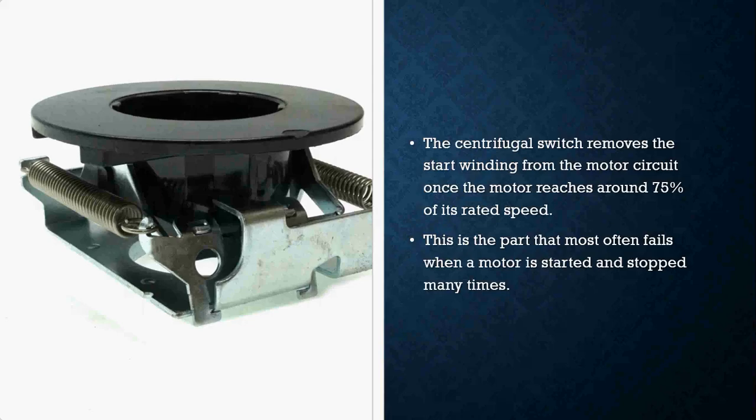Now, why do these things fail? It's because it moves. Remember, it's a normally closed switch, so every time that motor starts, that switch is going to open. Once that motor stops, it's going to close. It's going to keep doing that every single time that motor starts and stops. So eventually, over time, sometimes that switch will fail.